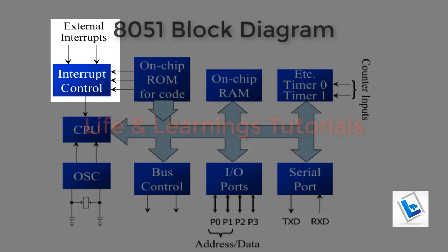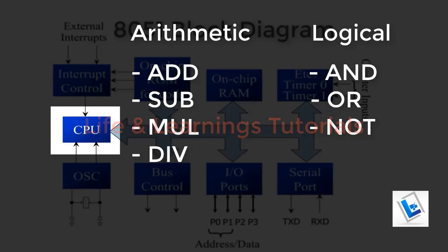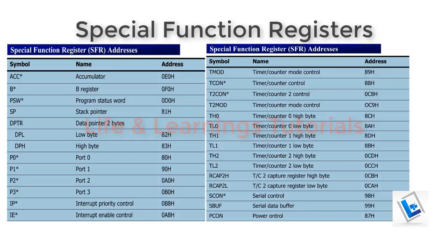If I consider the CPU of 8051, then it also supports arithmetic and logic operations such as 8-bit addition, subtraction, multiplication, division, ANDing, ORing, NOT, and other operations. There are some special function registers, also known as SFRs, and these registers will enable or disable a special function for 8051.